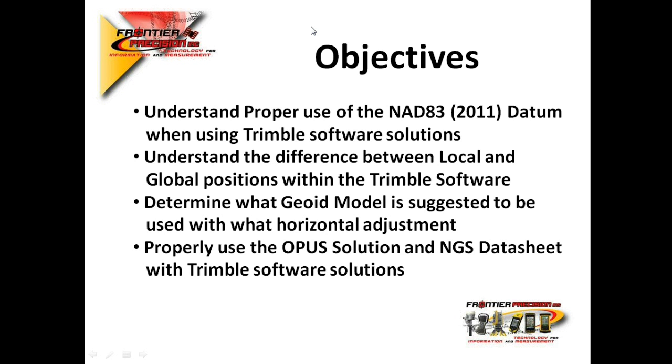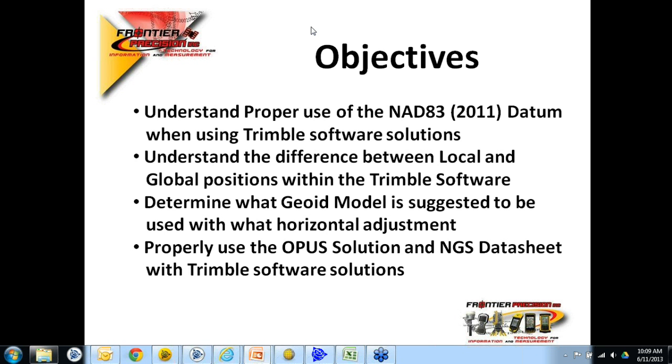The third objective that we want to cover today is determining what geoid model is suggested to be used with what horizontal adjustment. A lot of questions that we get are, hey, can I use Geoid 12A out in the field with every project? All right, and that's not necessarily the case. You don't always want to use the latest and greatest geoid model with every project, so we'll kind of cover that a little bit based on some suggestions that we've heard.